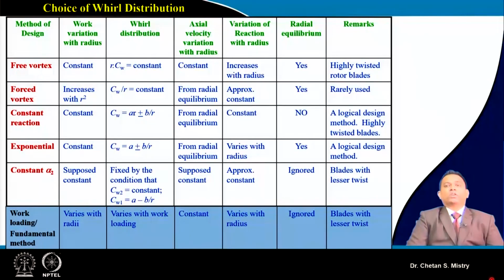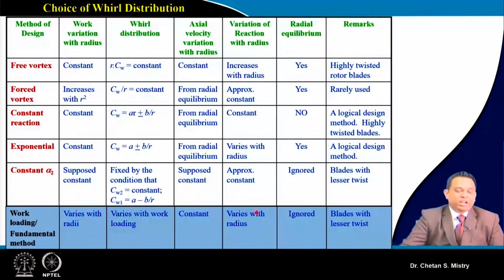This is the table that we made during our week 3. If you realize, there are different methods available for design of axial flow compressors, out of which for this particular numerical we opted for the free vortex design, using work loading, our fundamental method. Today's lecture will focus on the forced vortex concept.